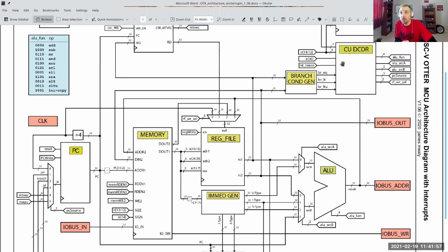And so how you coded that could create slightly different logic as far as how the synthesizer then makes the hardware that you described, right? So you described the same logic, but you describe slightly different hardware, which is kind of this sort of nebulous thing to wrap your mind around, right? That at the end of the day, everything you're doing in Vivado is you're telling the synthesizer how to build hardware, which is maybe an odd thing to think about.